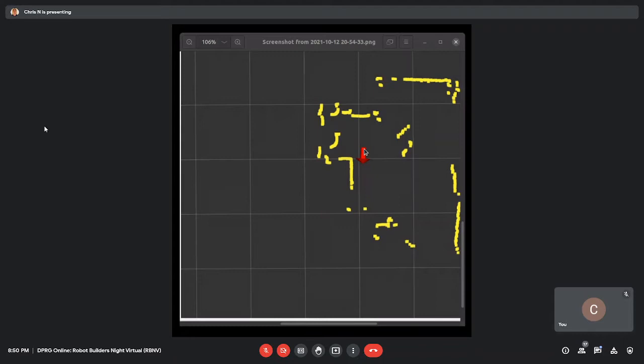So that's without any of the localization going on. It's just purely odometry, and it is what it is. It could probably be calibrated slightly better. You can see I don't have much of a heading error thanks to my BNO085. So just a little bit of offset, mainly an X, no, actually Y-axis offset here. All right, so that's as expected.